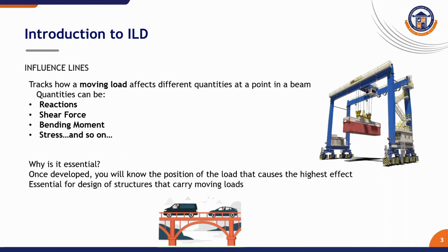So let us begin by defining our core subject. Influence lines are graphical representations that track the variation of a specific structural response, be it a support reaction, a shear force, a bending moment, or even a stress at a single specific point in a structure, as a standardized unit load traverses across it. Think of it as a diagnostic tool that reveals the sensitivity of a particular point in a structure to the movement of the load. Why is it so essential?